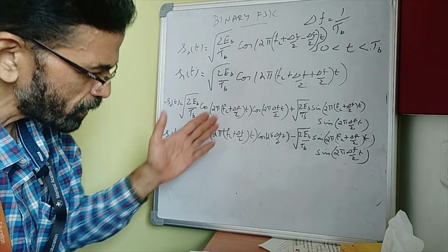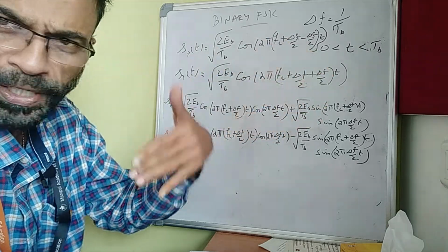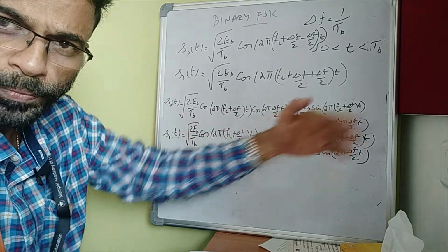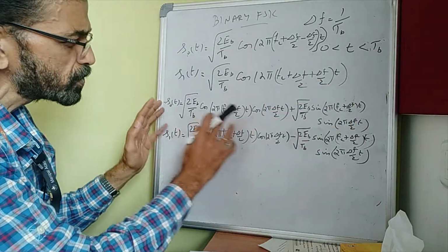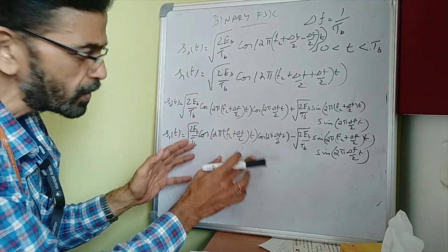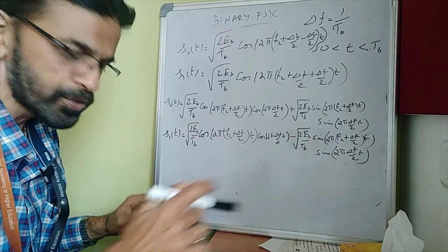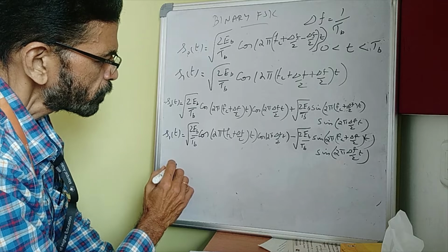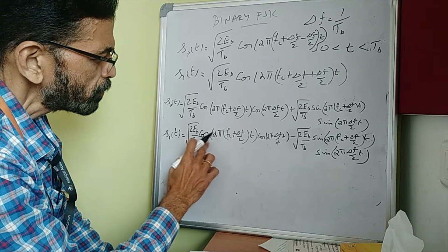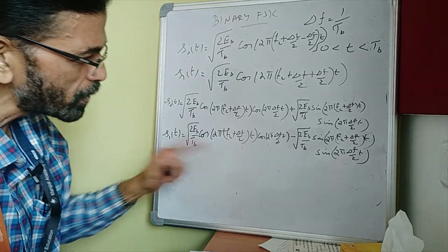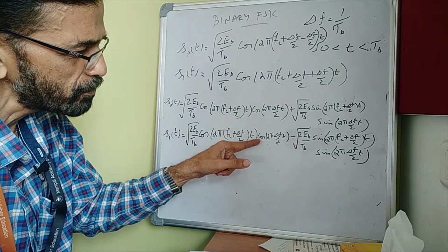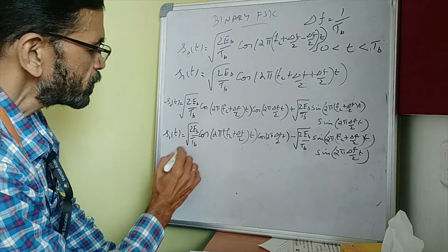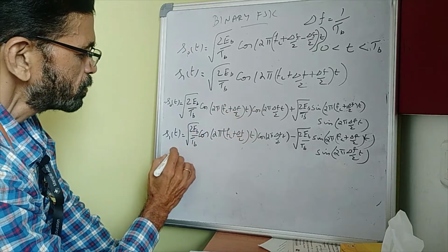So if you think I am first sending S0(t), then S1, then again S0, S0, S0, S1, some random sequence if you imagine, even then you see that this part will be there throughout. Which means that when you calculate the power spectral density of the binary FSK signal, this part will be there always. Effectively you will have a sine wave cos 2 pi (fc plus delta f) t multiplied by another sine wave which is cos 2 pi delta f by 2t.